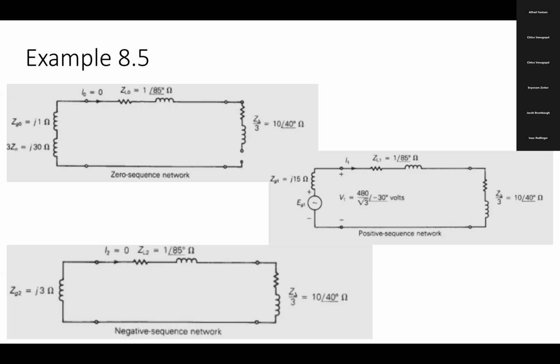Is it clear how to put them together? Okay, so this answers your first question. If it is a balanced network with no fault, then you will see I1 with some value, and I2, I0 as 0. If the fault hits the system, then you will see I1 rising to a very high level, and you will see some values in I2 and I0 because the system is going to be connected in a different way.